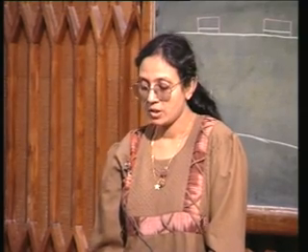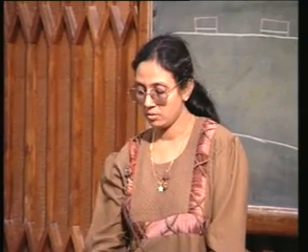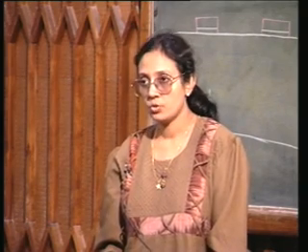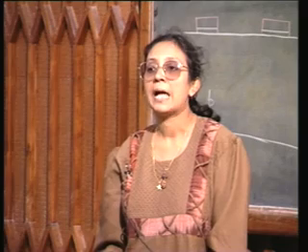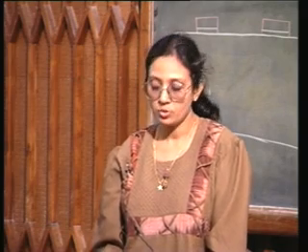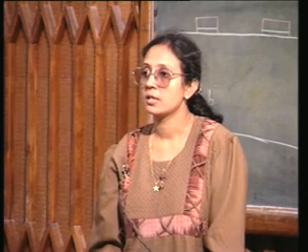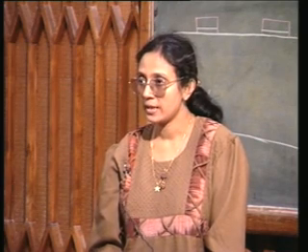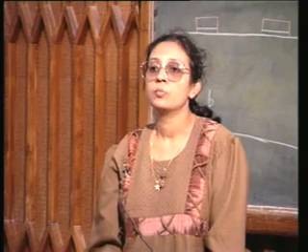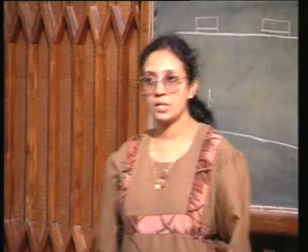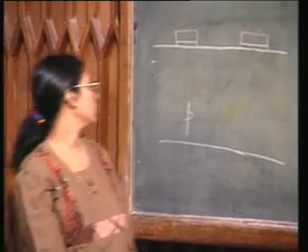After this, you can do a boron implantation. Actually this is a blanket implantation, that is, I do not use a mask. With this silicon nitride, silicon oxide in place, I carry out a blanket boron implantation. It is implanted P all over.